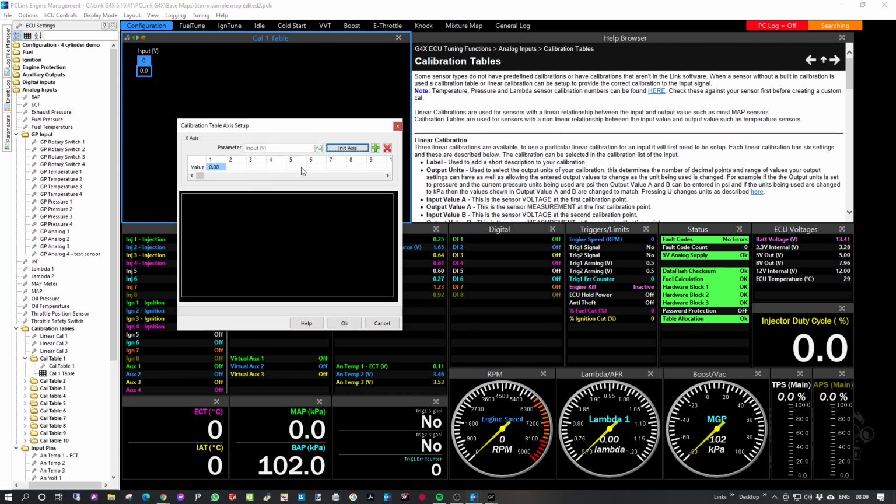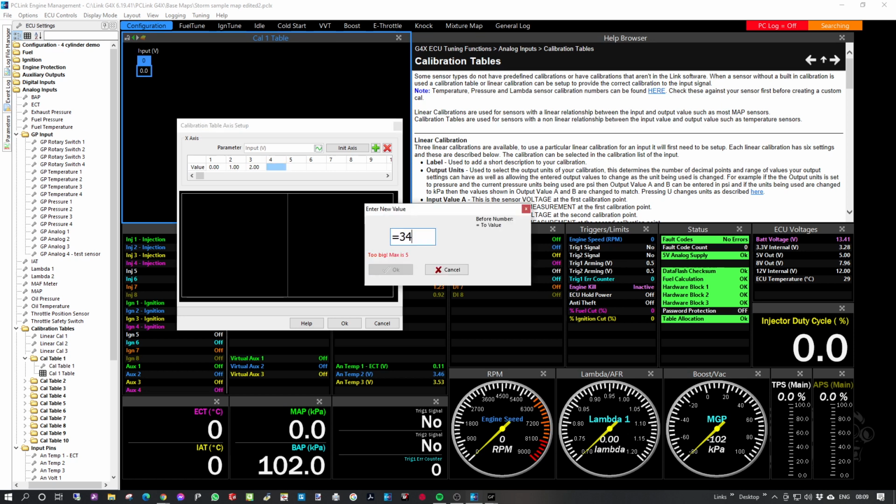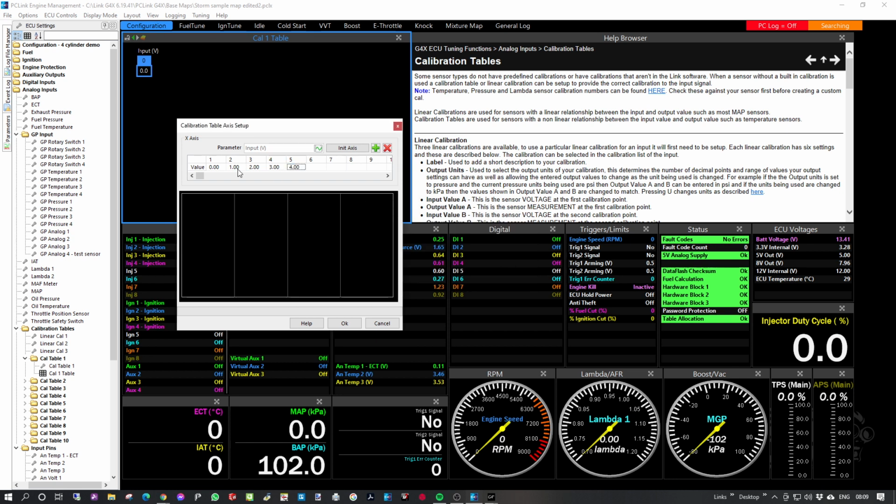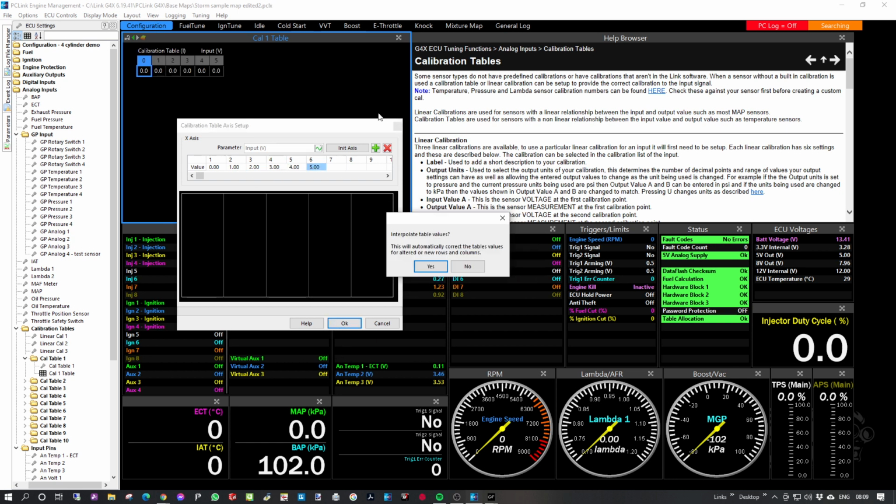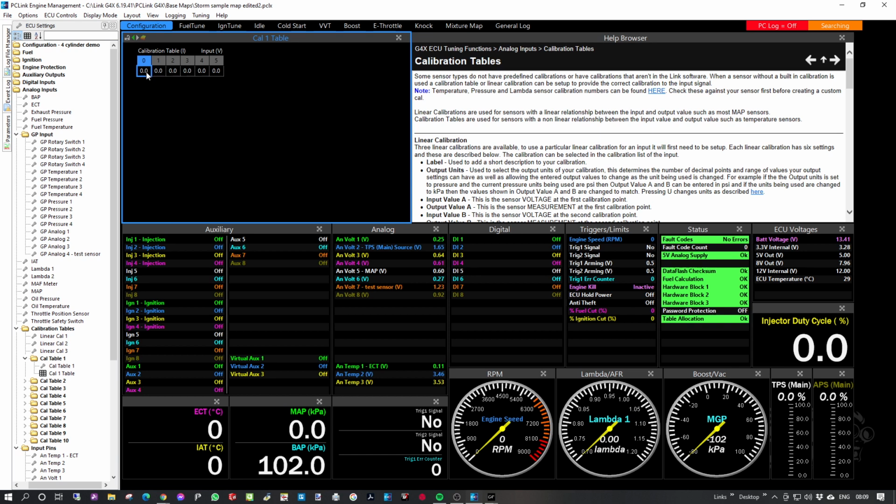Your calibration table can then be populated from 0 to 5 volts. And then you can say at 5 volts we've got 45 liters, and at 4 volts we've got 10 liters, and by using the shortcut key, and if any of you are familiar, Shift H is interpolate horizontal. It gives you that. That is another example of a GP input.